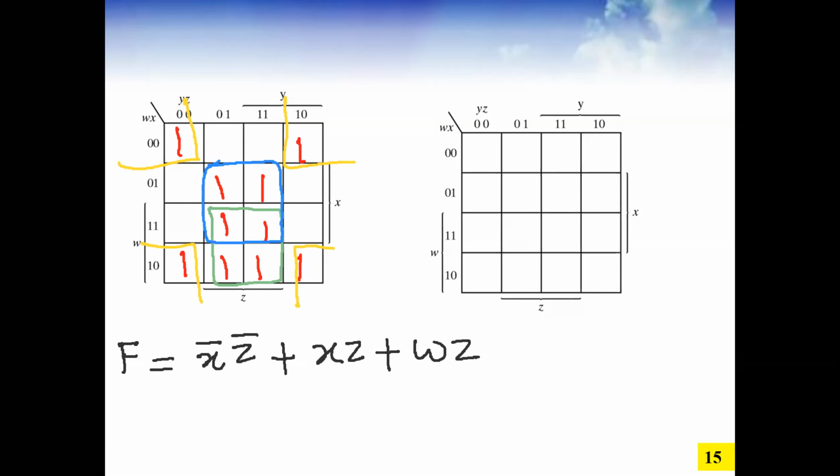So again, as per what I explained to you, first look for the yellow color and try to find, is there any minterm which cannot combine any other way? We cannot combine it another way, minterms 0 and 2, because we cannot compromise with the grouping. It is a part of a group of 4. You cannot make a group of 2.